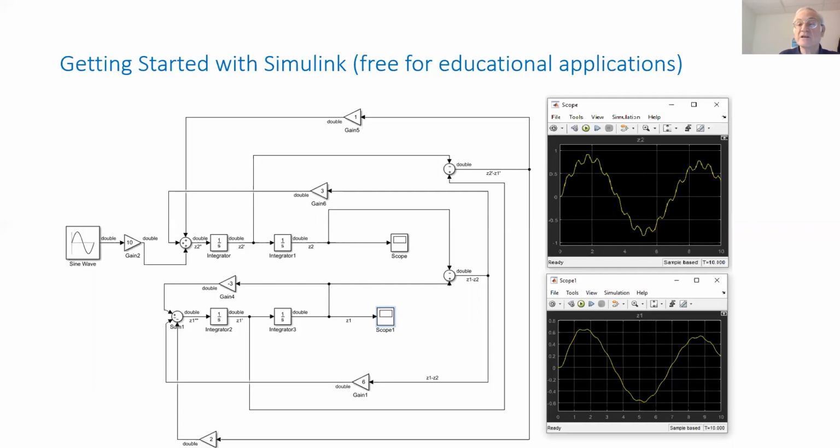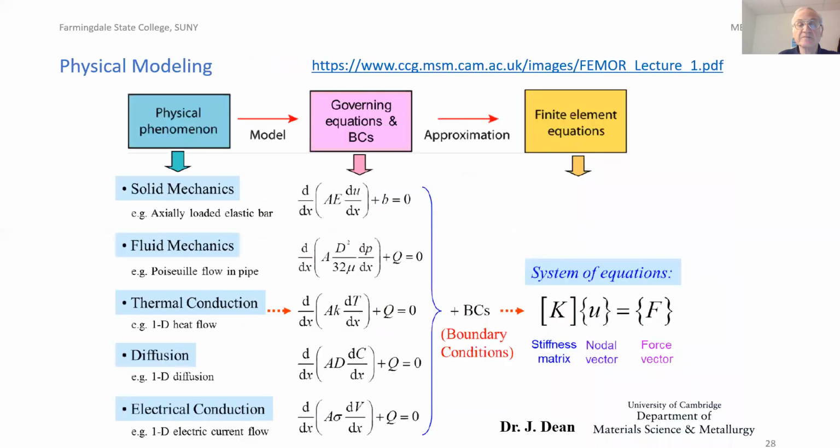Now, what we see in this particular example is that there are some vibrations, higher frequency vibrations, and of course, this will help us to design the parameters of the system such that the output function will be smoother, or perhaps put a servo controller that will filter out this vibration and provide us better dynamic accuracy.